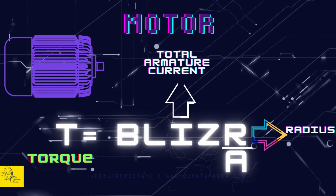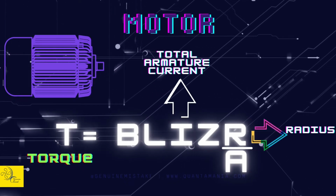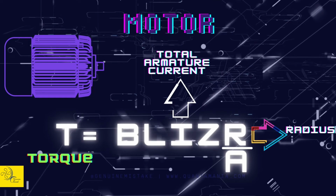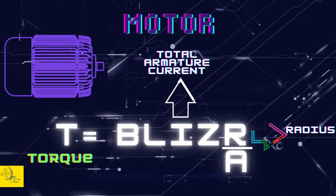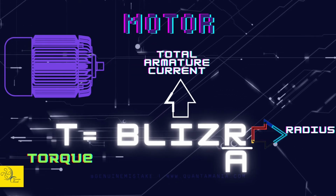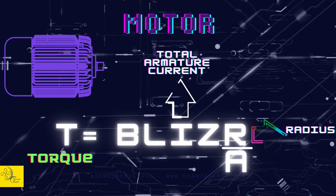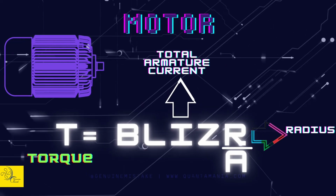To calculate the torque in a motor, we multiply B, the magnetic field strength, by L, the length of the conductor, by I, the total armature current, by Z, the number of effective armature conductors we know from the generator, by R, the radius, and divide it by A, all the parallel paths. So we can find the torque in a motor.